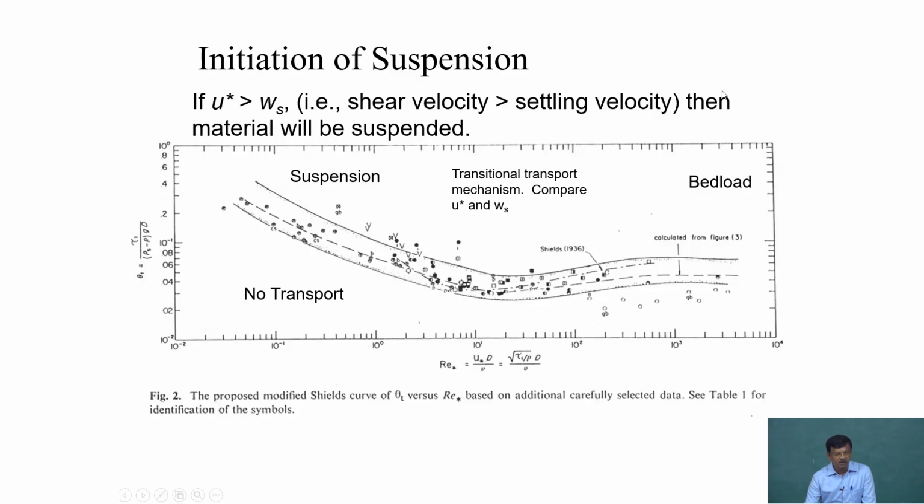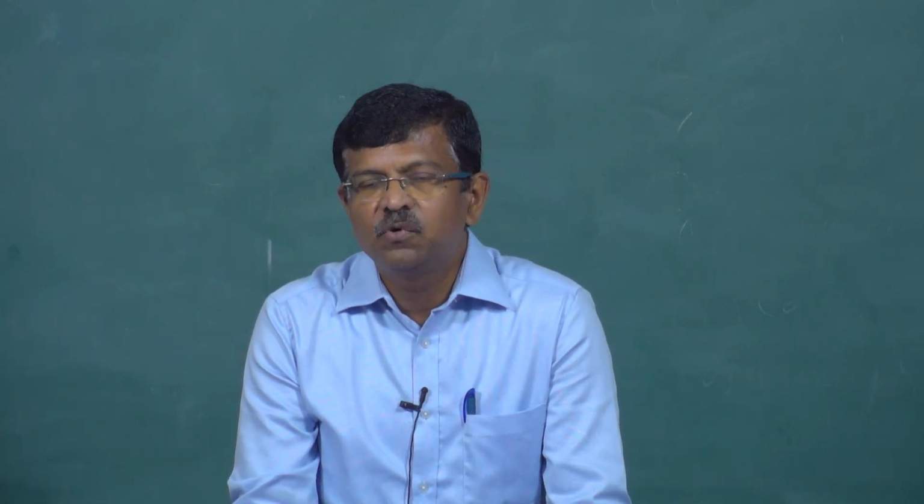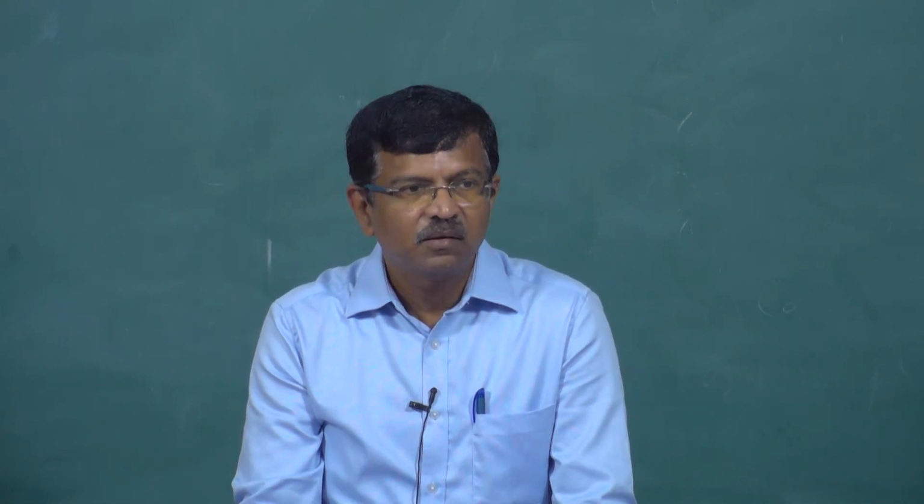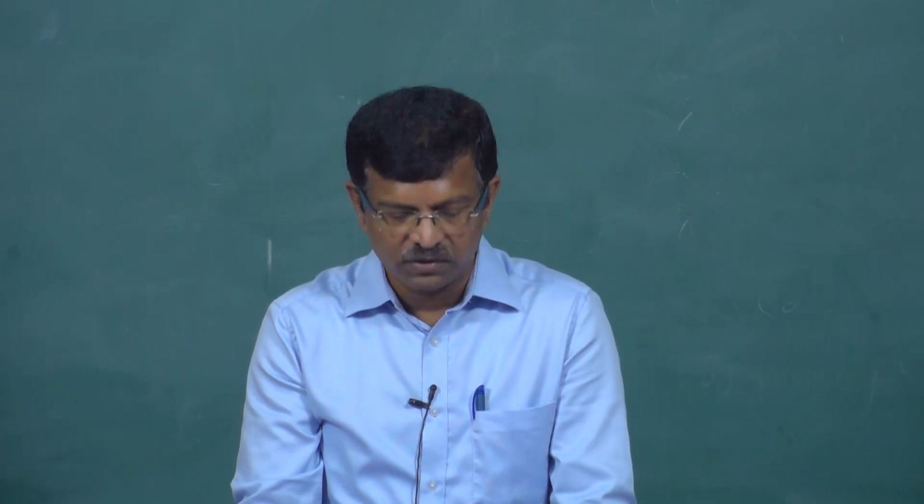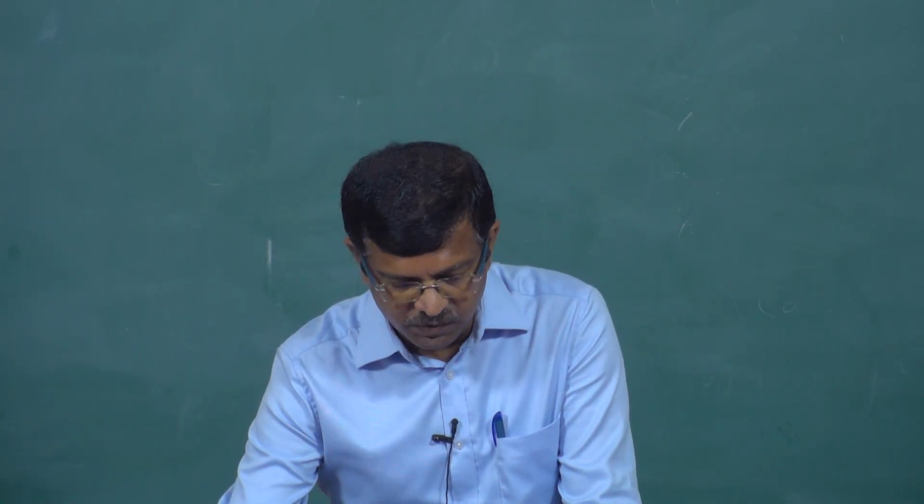Sediment transport can occur along the bed, with rolling of the sediment along the seabed itself, or once it comes to the suspension load, the movement will be about one order higher than the bed load transport. So, all these things are possible.